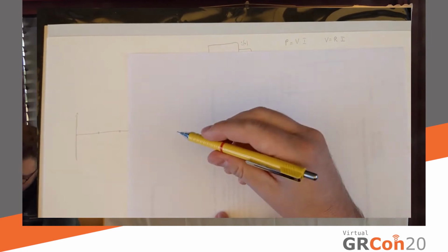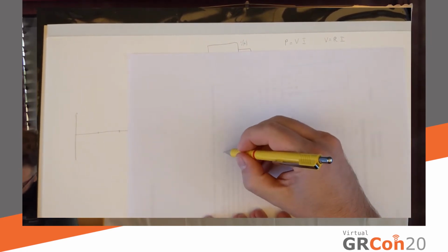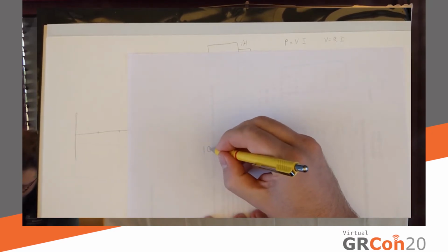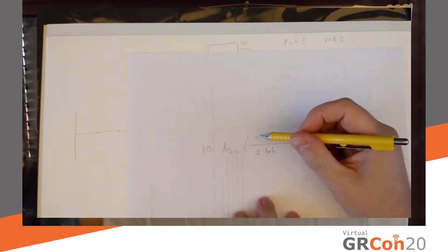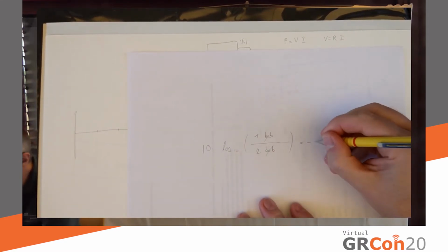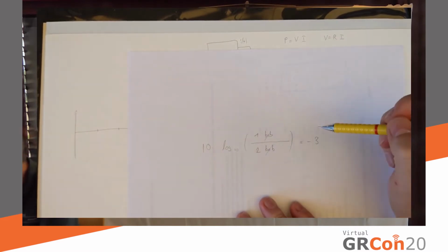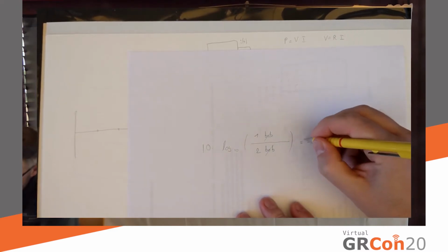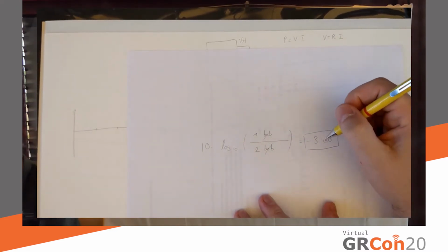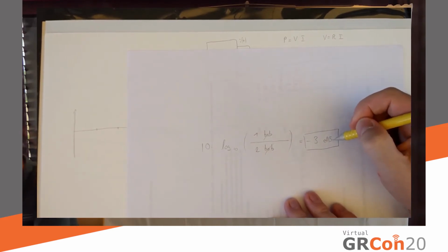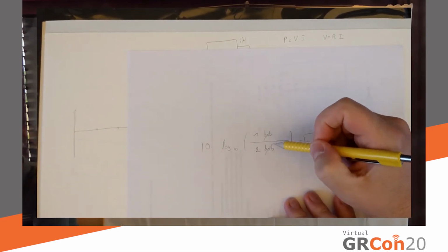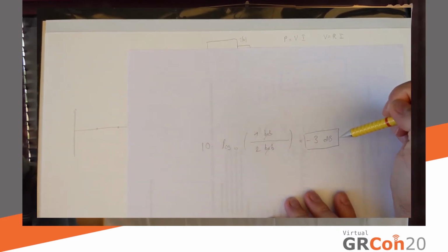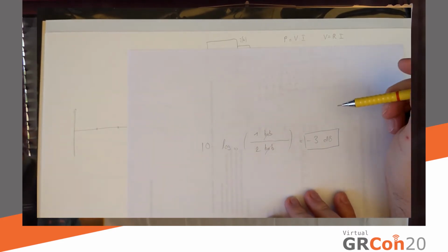I can also express this logarithmically in decibels by taking the logarithm of base 10, multiplying that by 10, and this equals -3. So log10 of 1/2 is approximately -0.3. Multiplied by 10 is approximately -3 dB. So I've reduced my beer by 3 dB, and this is important. I used beers because I wanted to clarify that this is nothing related to power or anything like that. This is just a ratio. Reducing anything by 3 dB just means halving.